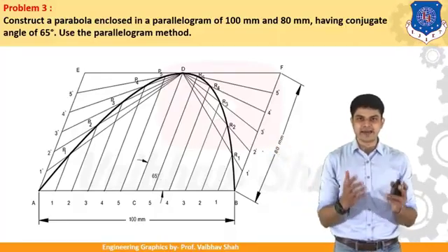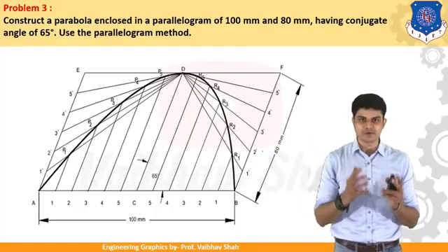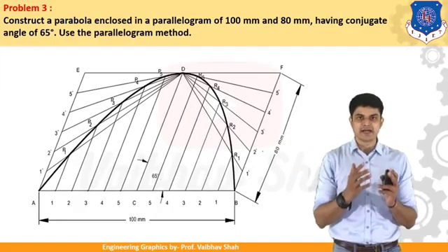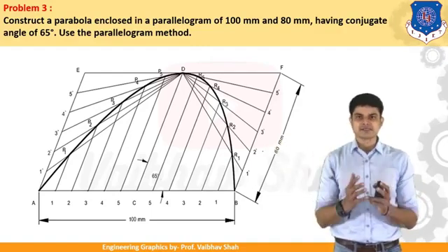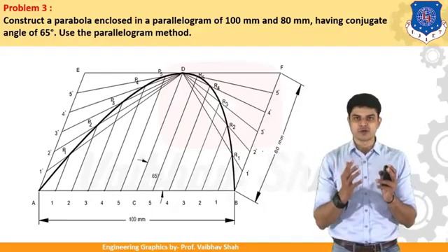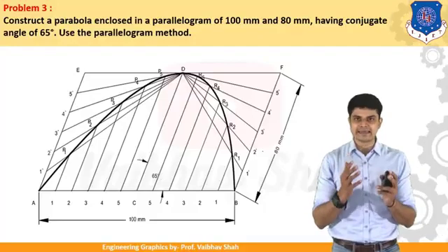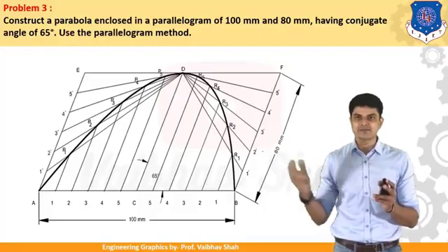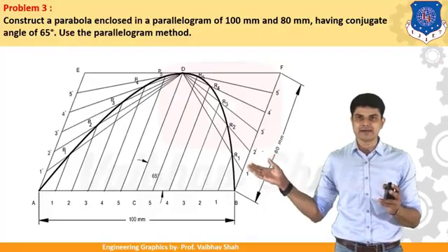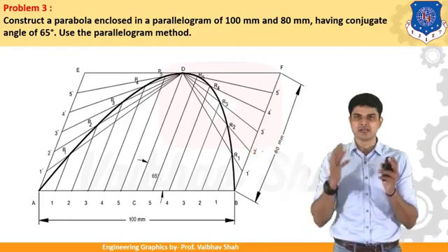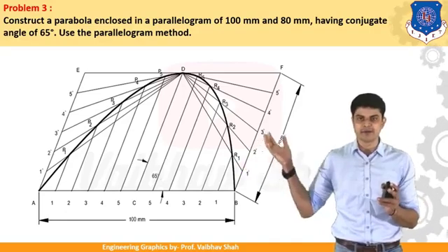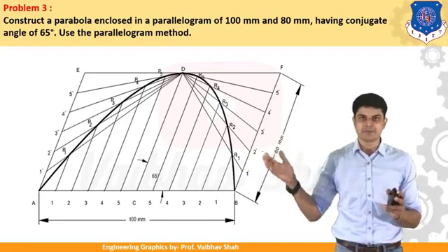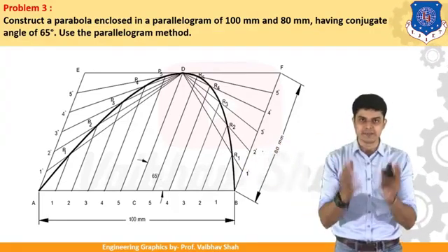Then it is very easy. We should draw one line from your point 1, which must be parallel to your line AE. You should use your roller scale or drafter. You should put your drafter roller scale onto the line AE and draw one inclined line passing through your point 1, which should intersect your line 1, and it will give you point P1. Then you should draw a line from point 2 to get your point P2. Then P3, P4, P5, and you can use similar methods.